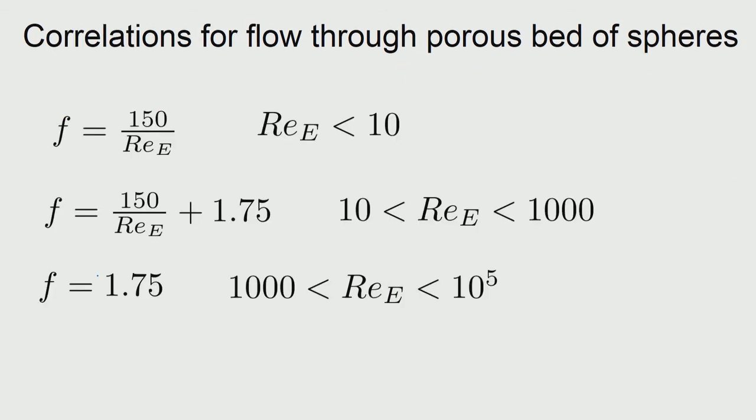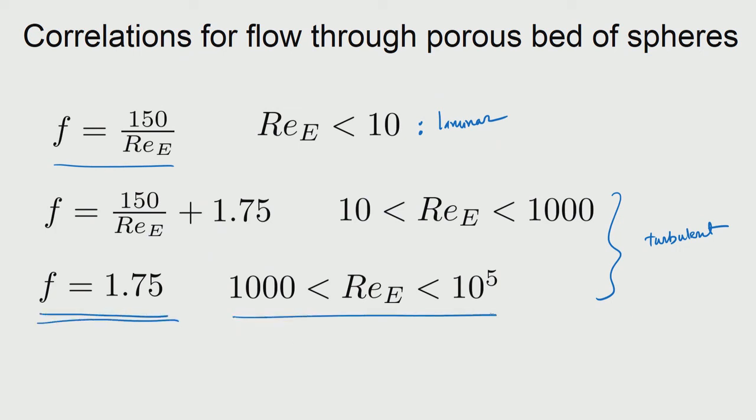So, the friction factor expressions are given here. For the laminar regime, you have them analytically derived, and for the turbulent regime you have empirical correlations, and we have a hybrid expression and a constant value. The constant value is of course for a very large Reynolds number, which means that for a variety of industrial problems we can use this assumption and solve problems.